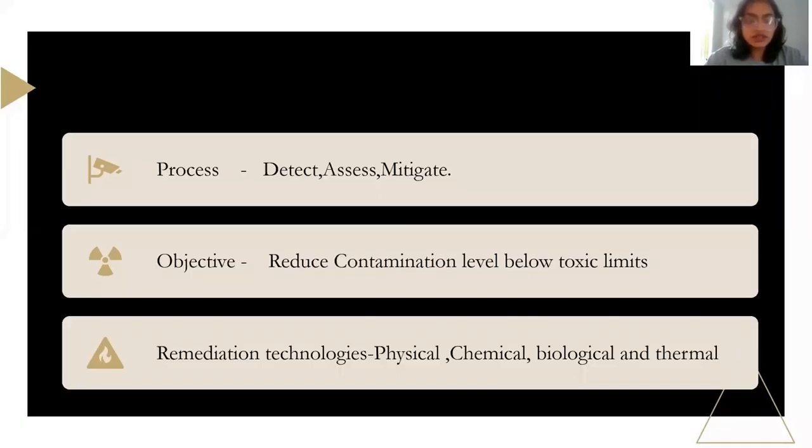Site remediation strategies are the systematic process to detect, assess, and finally eliminate the contamination from a site that has been polluted. It does not aim at entire decontamination, but at bringing the contamination level well below the regulatory toxic limit. There are a number of technologies to treat contaminants. Depending on the site condition and pollutants, the site remediation technologies can be classified as chemical, physical, thermal, and biological.